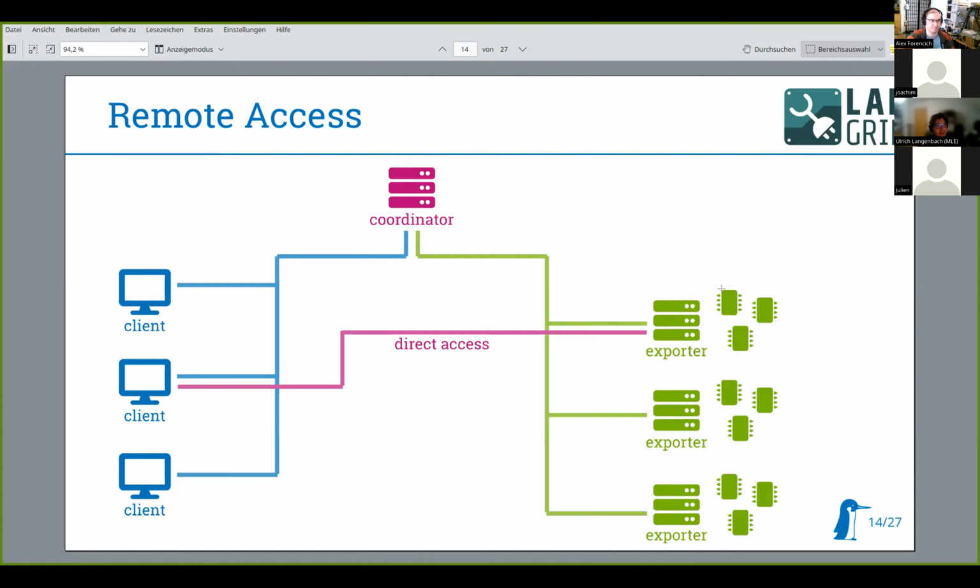So, for example, if you have a UART here on the top left of the hardware nodes, it's connected to one of the exporters, and it's assigned to a so-called place. Then a client can reserve or acquire this place and operate this UART, and that's tunneled via, I don't know what the actual tool is, the regular Linux UART over TCP tool. So it's just about grouping resources, making them available, reserving them, like coordinating access. That's what we use to download bitstreams onto FPGAs, and how we switch power on and off. That's the architecture of the tool, but it's not about running something somewhere. So that's a second layer, let's say.